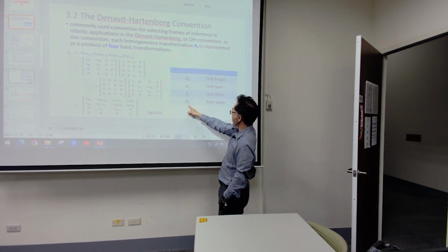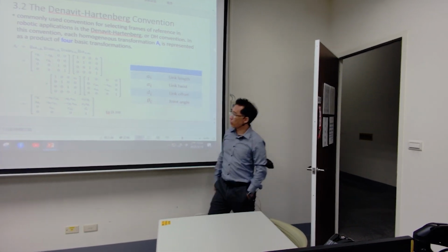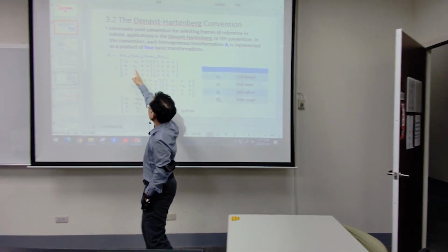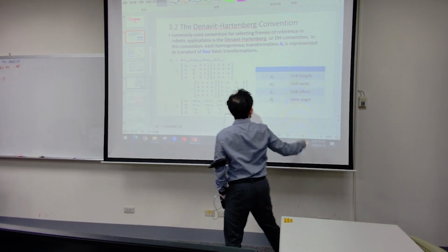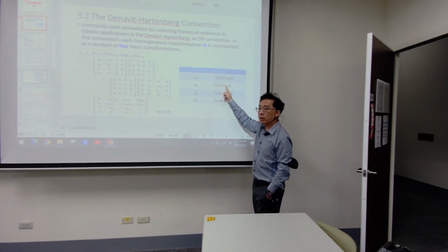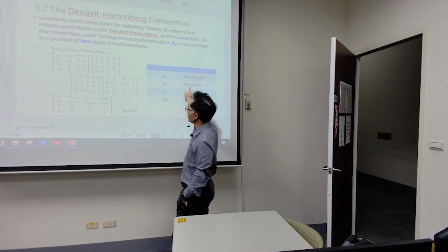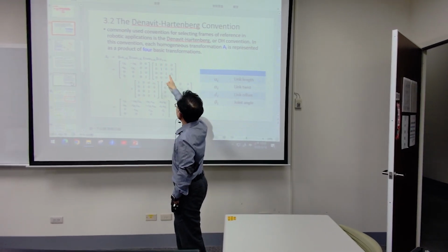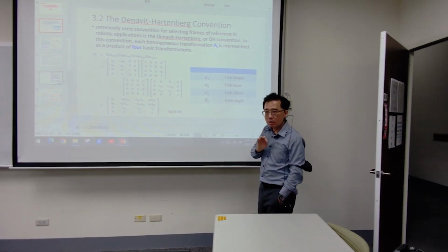So with these 4 parameters, you just retrace. This one is rotated about the z-axis, right? So you should take the z-axis and rotate by your theta. This alpha is twisted about the x-axis. So you should take the x-axis and rotate by your alpha. Make sense? Okay.